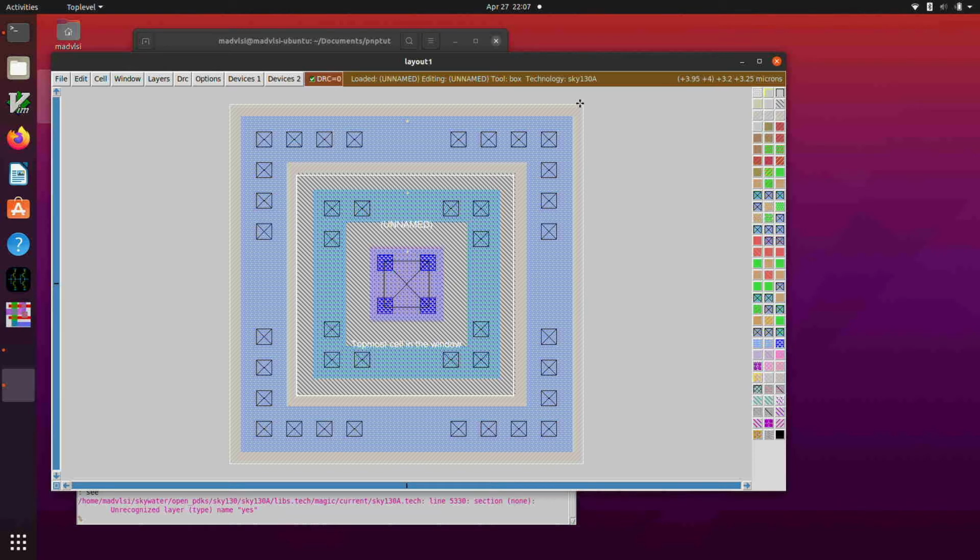And this area here, which has this opposite hatching, is actually a P well, which is just the P substrate. It's not any different than the P substrate. And inside this N-base region, there's a ring of N substrate diffusion, and these are N substrate contacts or N-well contacts.